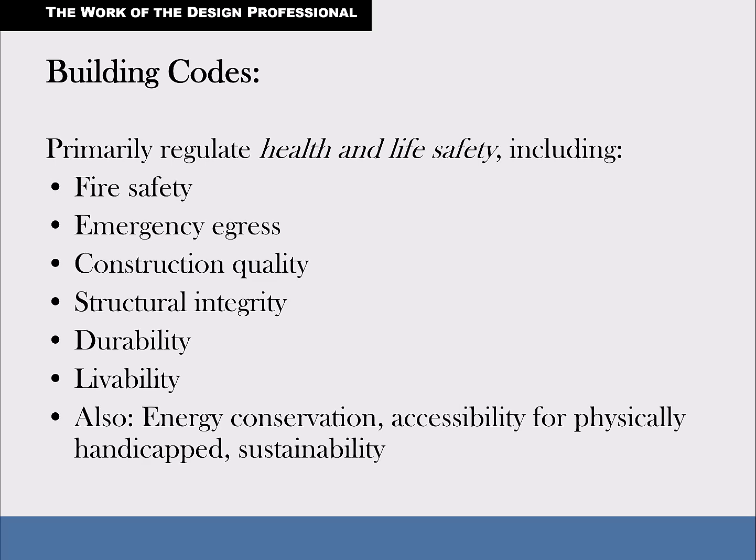But the emergency egress, you're talking about the ability to enter or exit, and usually it's more about the exiting in an emergency. And so when you have a bedroom, you have to have two ways out of that room. Either have two doors, or you have a door, which is normal, and a window, which is normal. And so that window has to be something you can get out of in an emergency.